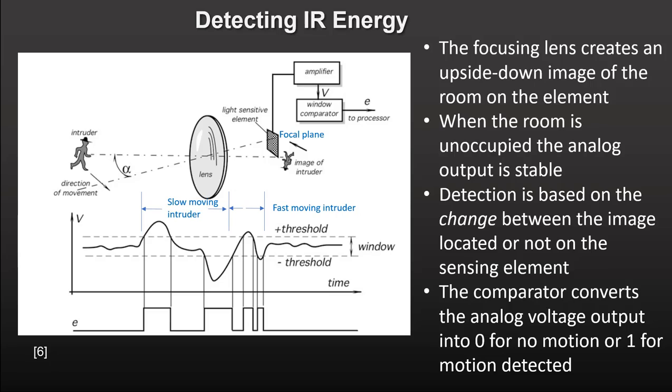The piezoelectric properties of the PIR element have a negative side effect. If the sensor is subjected to mechanical stress due to loud sounds or structural vibrations, it may generate a spurious charge indistinguishable from that caused by infrared energy. Your motion sensor could generate a false alarm. The police could come to your house and think you are the cat burglar instead of Oliver. Then you could spend the night in jail, which would not be fun.